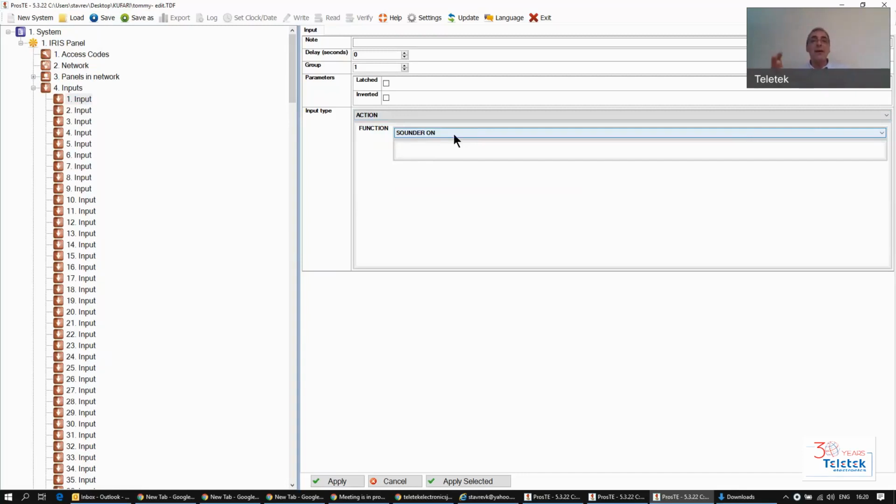when there is fire. But remember, you can set up delays for the sounders, delays that are used to investigate the zone and see if it's a false alarm. Upon receiving an event, fire or evacuation, you don't want to activate everything right away, because then it makes those delays for the sounders useless. So imagine you get a fire in zone number 1 that has a 5 minutes delay for the sounders. The security guard goes there, investigates, sees the actual fire, and presses a call point to bypass the delay and activate the system into fire mode or evacuation mode.